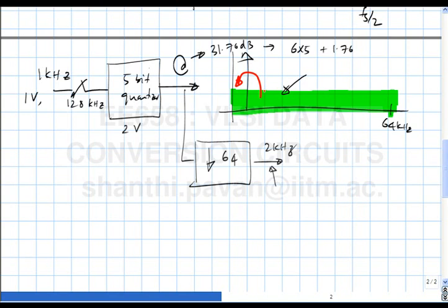So this stuff will come on here, this stuff will also come on here, because I am resampling, downsampling it, just dropping samples. You understand? So clearly the spectral density is going on adding up. What happens to the bandwidth? It is reducing, so what happens to the total thing? It should remain the same. Does it make sense?